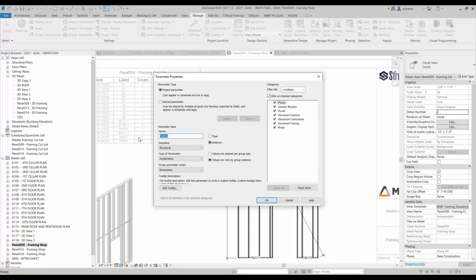Well, if you have the opening marker data set up as a variable by group instance, then you can technically do that. Even though the same group is being used everywhere, same model group, same floor plan, used for multiple floors from 1 to 5, my parameter can specify that that data is wrong for that specific parameter. I want it to be instance-based.